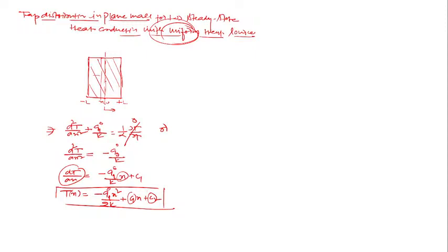And since uniform heat generation is there, at steady state, what happened? At steady state the rate at which heat is generated, at the same rate heat is transferred to the left and right faces. No accumulation should be there. And if the left and right faces were at the same condition of environment, h, T infinity, then there is symmetrical boundary condition I should use, yes or no? And the surface temperature will be the same here. The two constant boundary conditions.